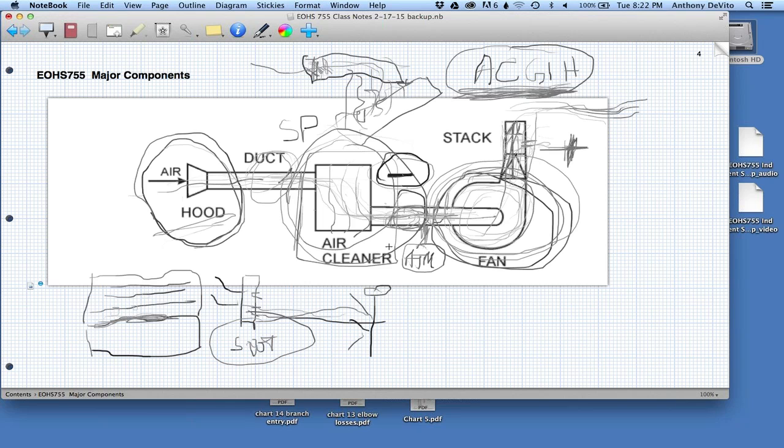Okay, if I was going to design this ductwork, I might want to put round ductwork on one side and rectangular ductwork on the other side. Which side do you think we prefer to have the round ductwork? Is it more important on the suction side or the discharge side? Remember that the same quantity of air is always going to move through these, and unless we change the cross-sectional area of the ductwork, the velocity is always going to be the same. Let's assume the same cross-sectional area, whether round or rectangular. Yeah, I'm going to want round on the suction side.